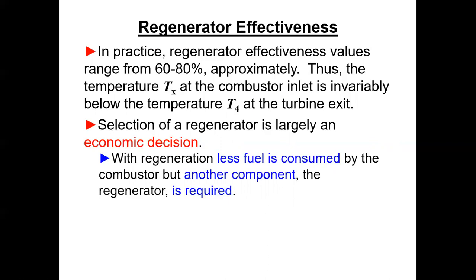Like a company hires you and they say, okay, we know this boiler is inefficient. It could be an economizer on a boiler that takes flue gas and preheats feed water with it. So, you know, how big a one should we buy? The big one's 400,000, the littler one's 300,000. And of course, the big one gets you a 40-degree boost in feed water, and the little one gets you a 30-degree boost in feed water before it goes in the boiler. What do you think?